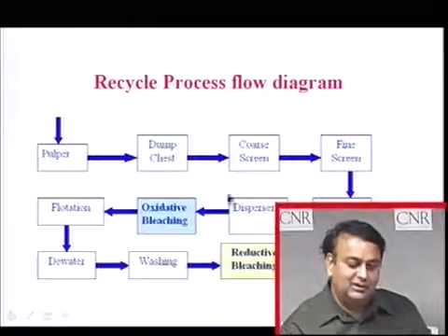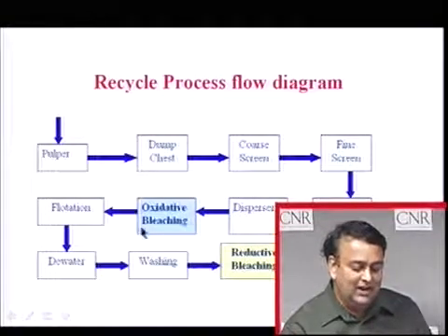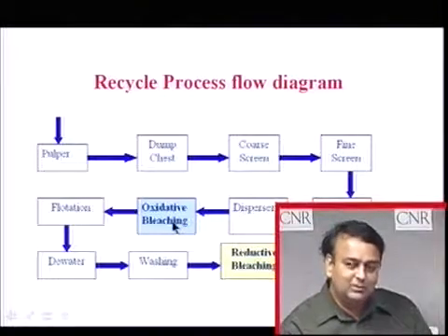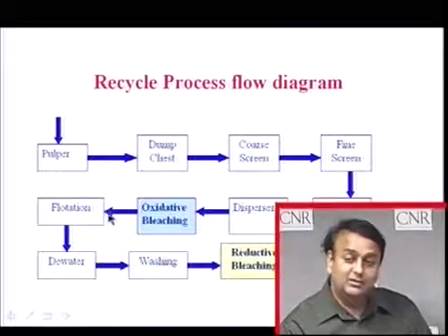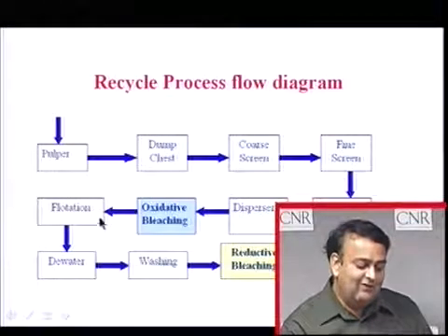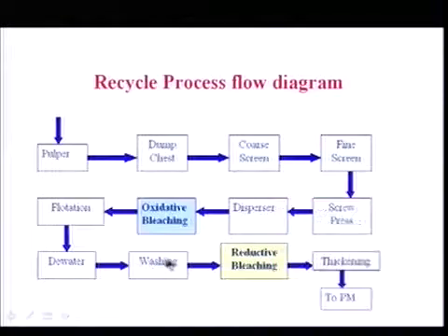The disperser is used as a mixing device, and temperature and consistency help, then it is sent through a retention tower where the oxidative bleaching takes place. Right after the tower, your pH will be somewhere between 8 and 9, which is ideal for flotation, and then after flotation you do the dewatering and thickening again with a washing device. Now it is 10% consistency and the residual peroxides are removed, it is ready for reductive bleaching.